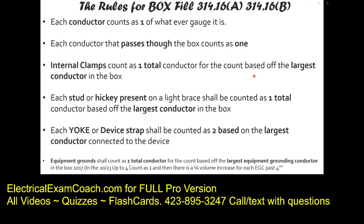So if I have 10s and 12s, it's only going to count as one number 10. Now in the 2020 and in the 2023, it's a little bit different. Up to the first 4 conductors, it's going to count as 1. Then for every one that is past 4, you're going to increase it by a 1/4 inch volume. And we're going to do some practice questions with these. Just let that soak in, and when we get to the practice questions, we're going to expound on it more.